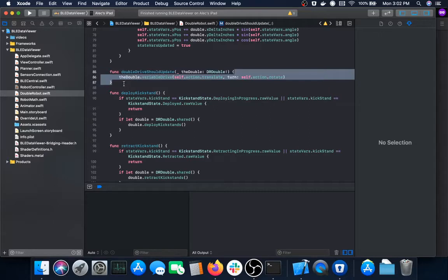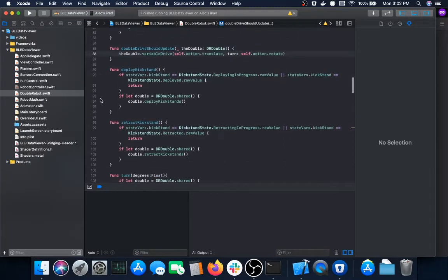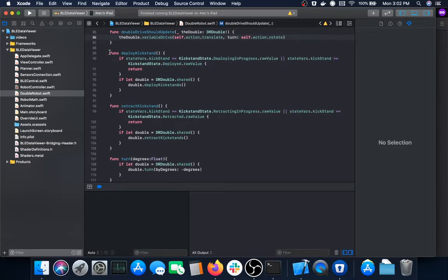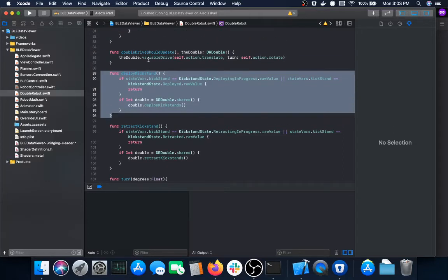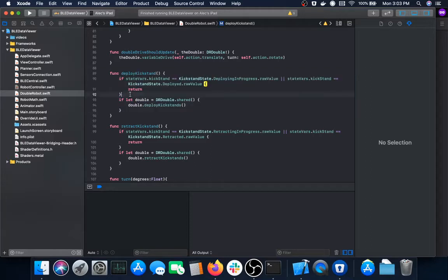So yeah, it's kind of detached. You set the action separately from where the robot actually reads the action. But it seems to be fast enough in all of our situations that the control system is still stable. It's not oscillating or anything like that, as long as the control actions are not too high.